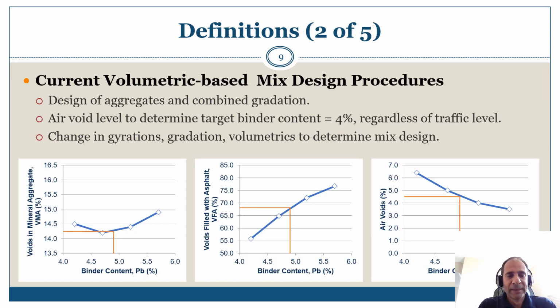Let's start by looking into the current standard, the volumetric based mix design. So whether the mix design is developed through a Marshall, Hveem, or Superpave mix design process, there are basic volumetric requirements that the asphalt mixture must be designed to meet. Each of air voids, voids in mineral aggregates, voids filled with asphalt must fall within a specific range in order to have a successful asphalt mix design.